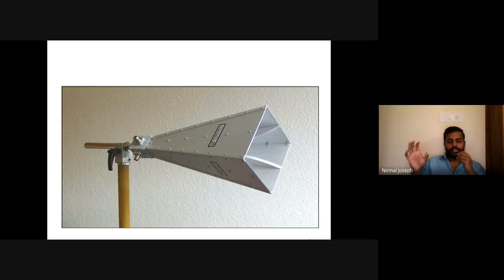Then you have to say about E plane, H plane, pyramidal, then conical, all these things. Then some design parameters, from that a basic question: L plus delta, where delta is the difference between the actual wavefront and the edge of the horn antenna, not conical, the edge of the horn antenna. So these are all the things we have to remember in horn antennas.